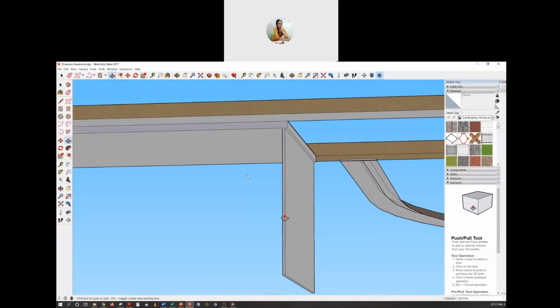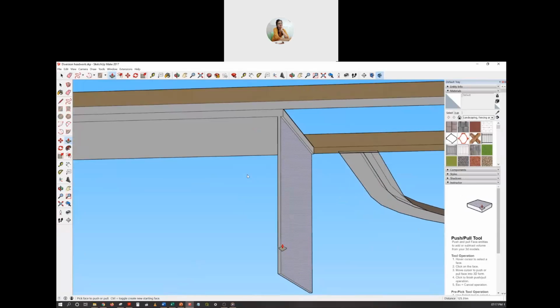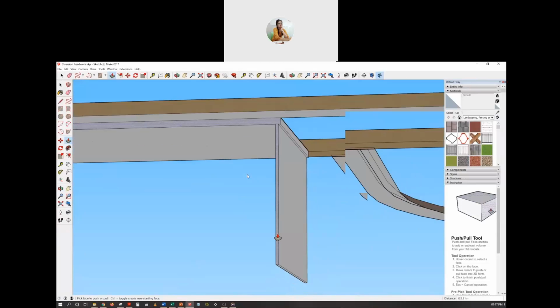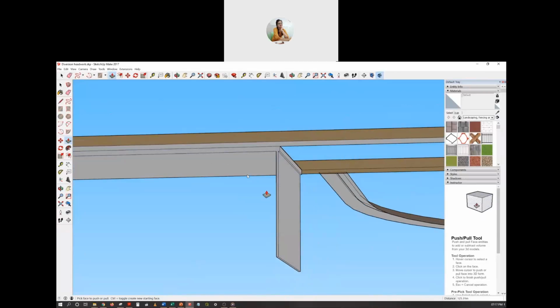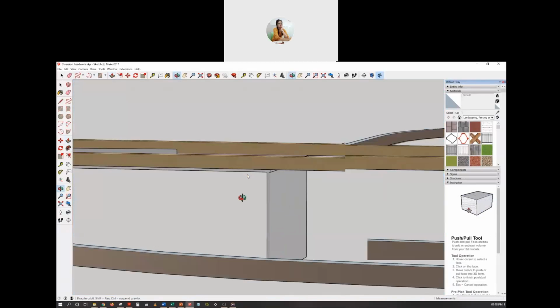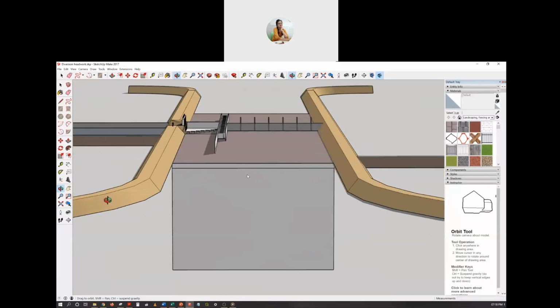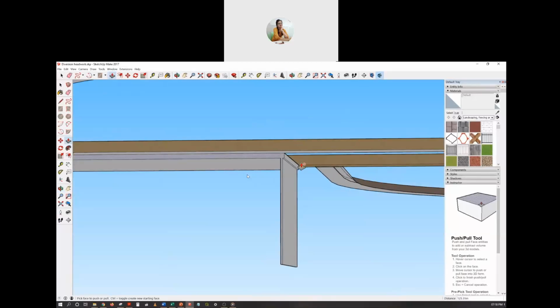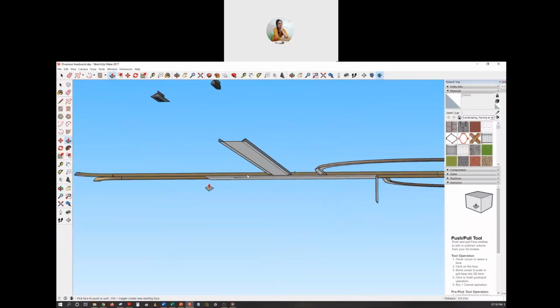The sheet pile will not have this kind of thickness, but here in the drawing, just to show you, I'm giving it some thickness. So this will be an underground wall or sheet, so that when water enters here, it cannot directly flow horizontally. It has to go down a little bit, then again come up, then only it can flow horizontally. A similar sheet pile can be provided